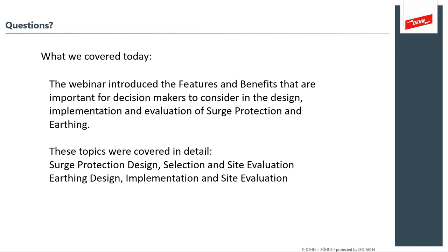And definitely with older facilities, you want to pay even more attention to the earthing pigtails and inspections of things that are visible, that you can actually track. Yes, in our experience, that would be a much higher problem, is that these older installations and older facilities have very weak or damaged grounding connections and grounding grids. So fixing and implementing a proper grounding system would be the first thing to address. Absolutely agree with you, Mark.